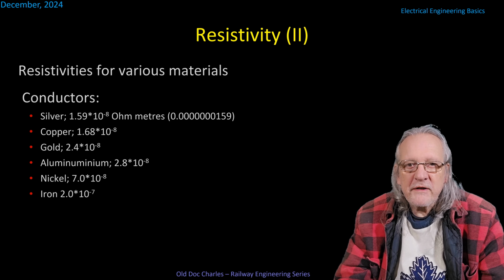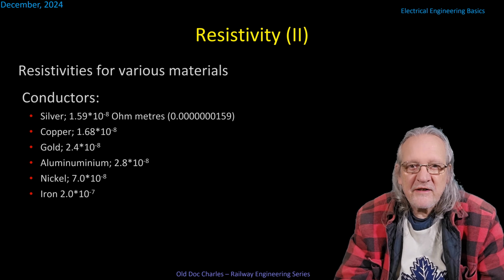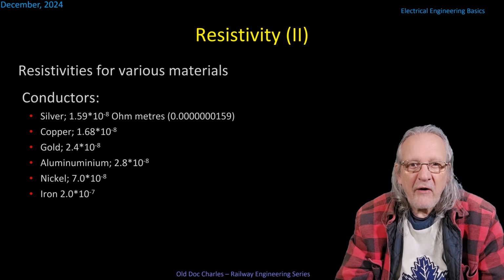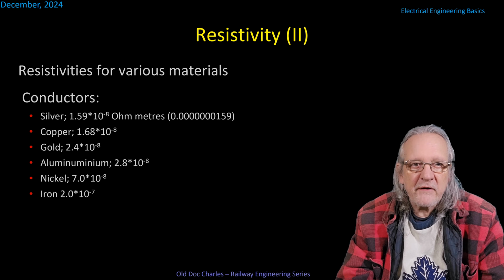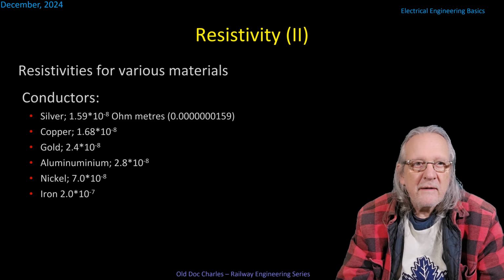We use gold specifically on contacts and that, because unlike the other materials, gold doesn't rust or tarnish or oxidize, whichever word you want to use. So it stays the same and stays clean and doesn't become contaminated with oxides of itself, like silver, copper, and aluminum can do.